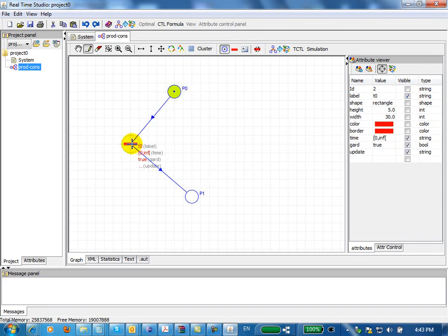For a transition, it has attributes. Also, you can play with the color, the size of everything. It has a time, the firing interval, which in this case is from 0 to infinity, but you can change it if you want. And you have other properties which are going to be used later on in more sophisticated types of Petri nets. Actually, it's what is called the Interpreted Petri Nets. We can set a guard, which is a condition, or we can even have an update on variables.